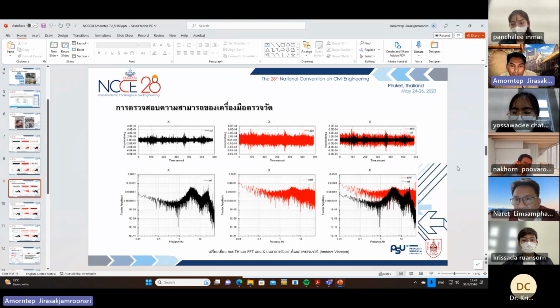If you want to make a measurement of ambient vibration, then 0.2 is important. But if you want to measure an earthquake or wind or storm, I think 0.2 is not so important, because the amplitude of that force is higher than 0.2 milli-G.